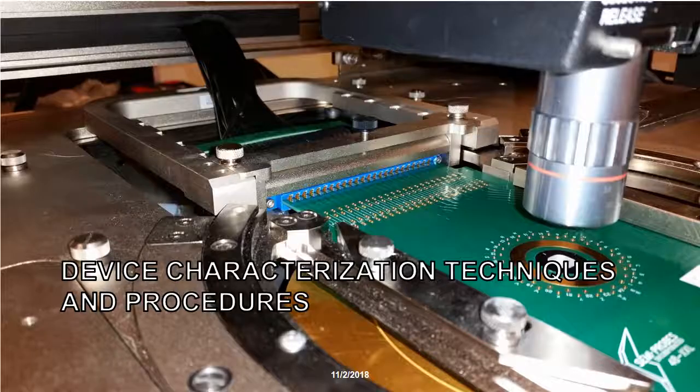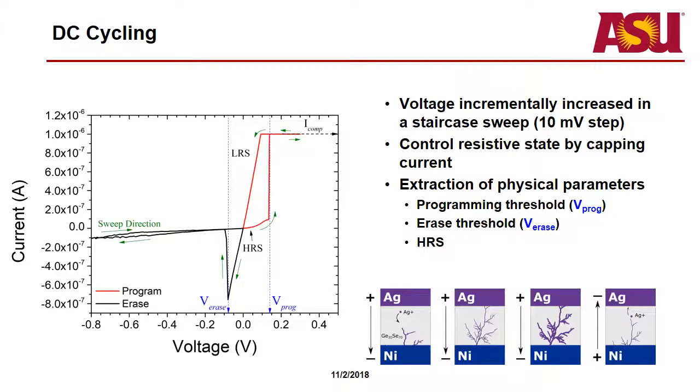Okay, so next I'm going to get into how we test these devices electrically. So one of the methods for programming these devices is to do DC cycling, and so that consists of doing a voltage sweep from, say, 0 to 0.5 volts and back, and then, say, 0 to some negative voltage and then back to 0. And then from those characteristics, we can extract important parameters such as the programming threshold, the erase threshold, the high resistance state, and the low resistance state. And the low resistance state is actually dictated by a compliance current that we limit using the parameter analyzer.